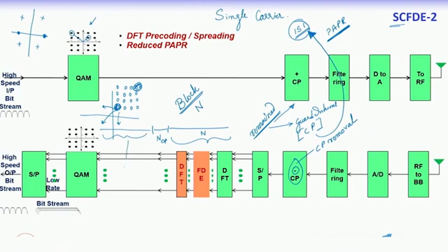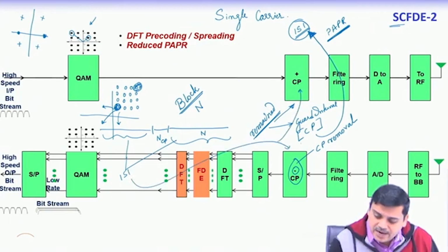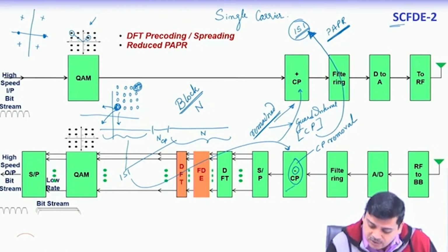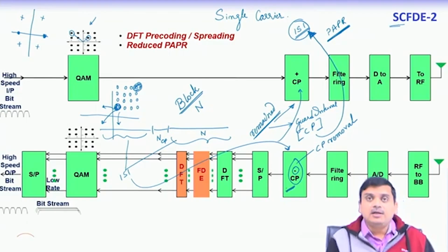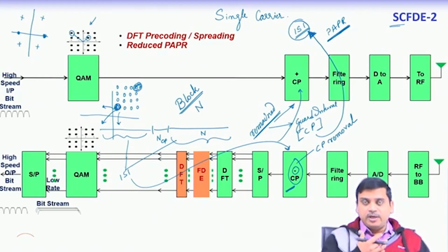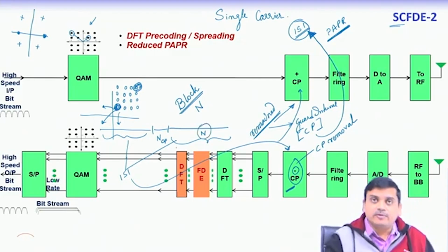Okay. So, the ISI between this and this is addressed by the CP that is added and removed. Now, one would argue that one has to apply ISI cancellation, but look at this, since we have got this CP, right, our earlier discussion was that linear convolution in the time domain gets translated to circular convolution in the time domain. That means, if we do a DFT operation, it would appear to be the DFT of the channel coefficient matrix multiplied by the DFT of the received signal, all with n point DFT. This is something we have to remember, right.